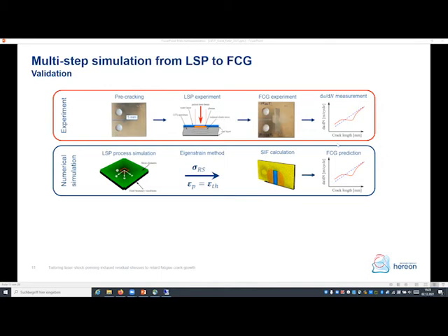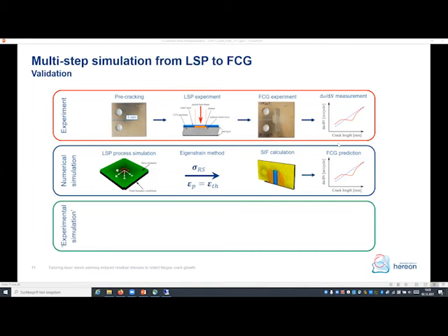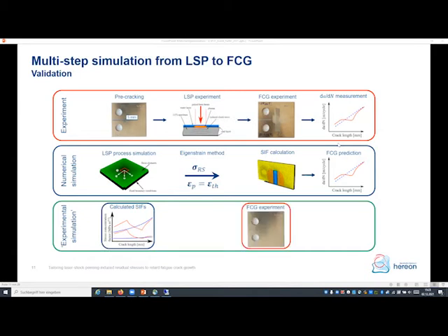So for further validation, I use stress intensity factors that are calculated for a peened specimen with residual stresses with a numerical approach, and I take a specimen from the experiments, which is not peened. And then I apply these calculated stress intensity factors of a peened specimen, calculated by the numerical approach, to the real experiment of an unpeened specimen. And this simulates the effect which residual stresses have on stress intensity factors. And then I get the fatigue crack growth rate as well. And this experiment is named experimental simulation here.